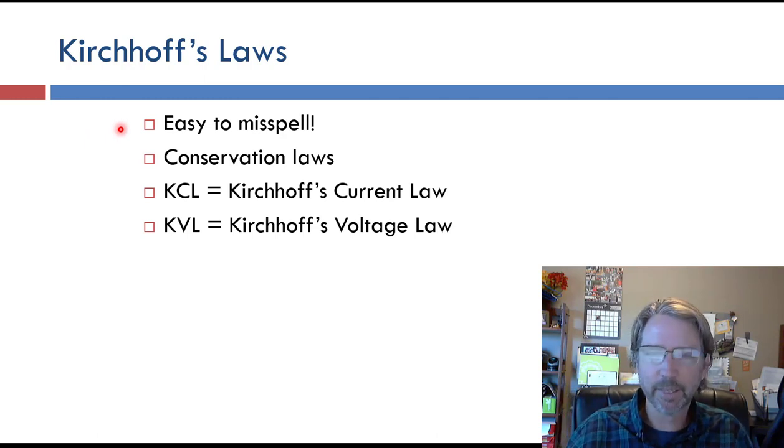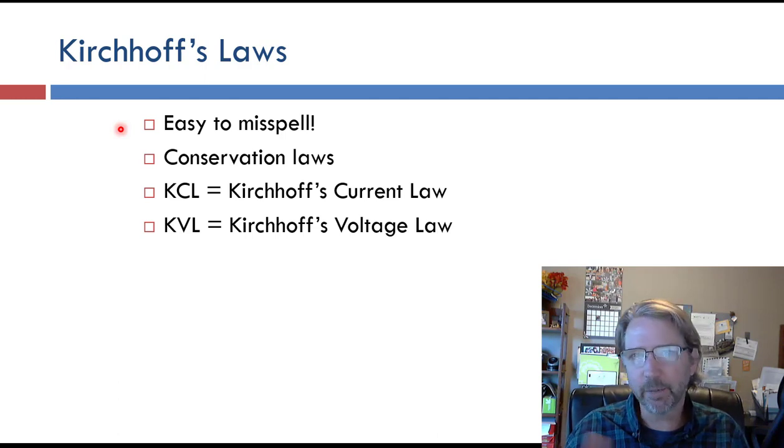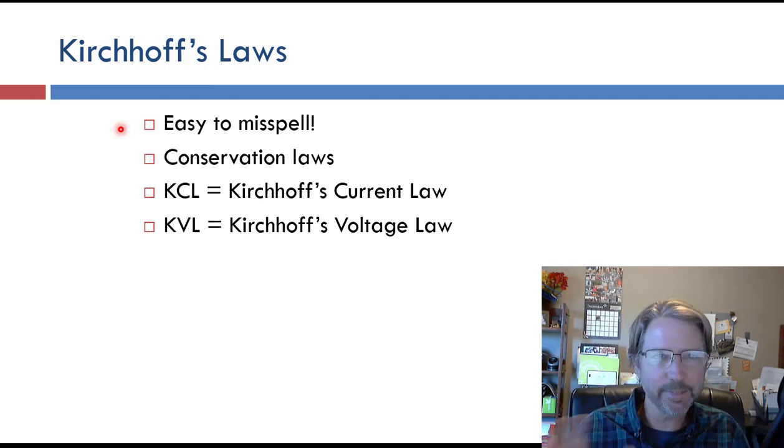There are 2 Kirchhoff's laws, and they're basic conservation laws, saying that energy isn't created or destroyed, or in a system we conserve energy. And so we have Kirchhoff's current law, which we'll abbreviate in this class as KCL, and Kirchhoff's voltage law as KVL. Hopefully you saw these in the physics class. That's the prerequisite for this class, but we'll do them again. It's worth seeing. These are really powerful. Kirchhoff's laws and Ohm's law form the basis of all of our solution methods going forward. So with those 3 laws, KCL, KVL, and Ohm's law, we can do all the analysis coming up.